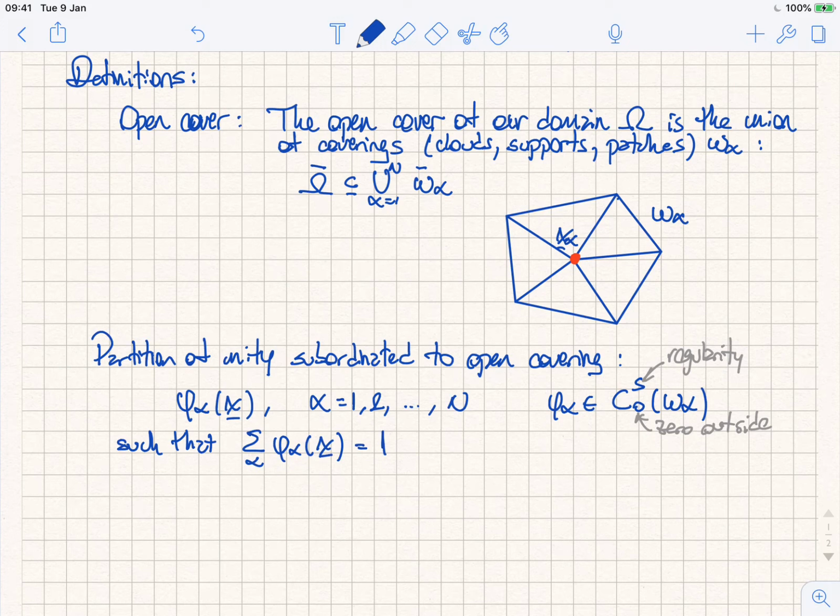So if you take all those functions and you pick any point in your domain, this holds true. For the shape functions that we're using in standard FEM, you just take Lagrange elements, linear elements, quadratic elements, cubic elements. This holds true for any point in the domain. So all of those are partitions of unity.